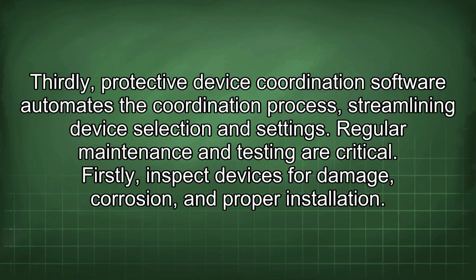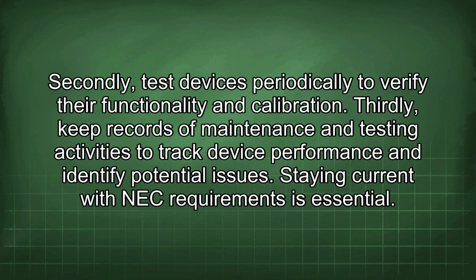Regular maintenance and testing are critical. Firstly, inspect devices for damage, corrosion, and proper installation. Secondly, test devices periodically to verify their functionality and calibration. Thirdly, keep records of maintenance and testing activities to track device performance and identify potential issues.